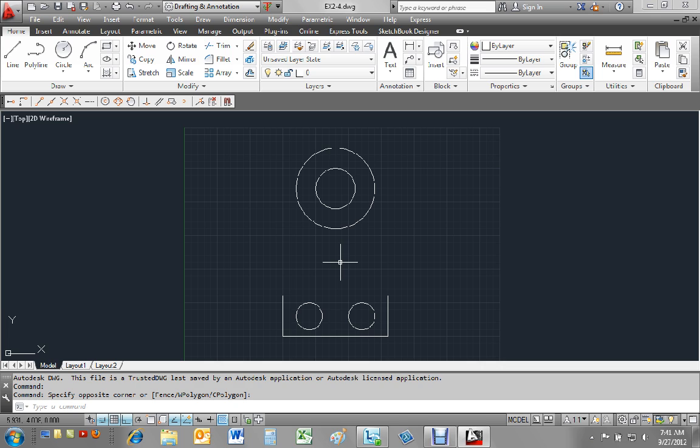So to be able to do that large one on the outside, the 3.5-inch radius, and make it pass through this point right here and tangent to here, we will use a geometric construction technique that will add the radius to our large circles here, and then we'll create a radius from this point here. The intersection of those two large circles out here will give us a center point from which we can draw the tangent 3.5-inch radius.